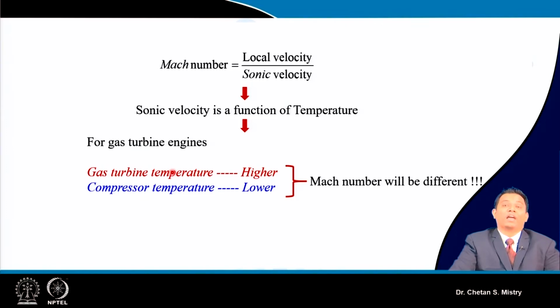Now we realize that turbines mainly act like a nozzle. The flow coming out of the combustion chamber passes through the nozzles or nozzle vanes, which accelerate the flow, and that accelerated flow strikes the rotor. Based on that rotation, we generate our power.